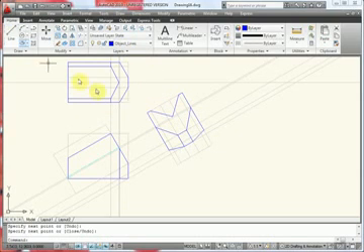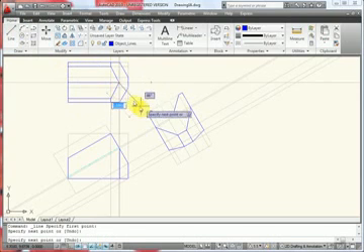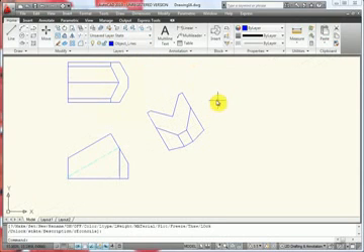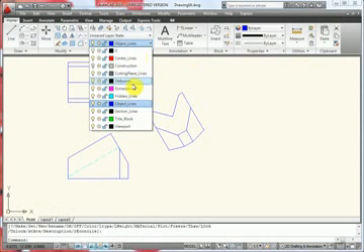One more line I have to draw, I just noticed on this top view, that shows the bottom of this V block. Press the escape button. Now I'm going to turn off my construction line layer, and I'm going to now dimension it. So I'm going to switch to my dimension layer,